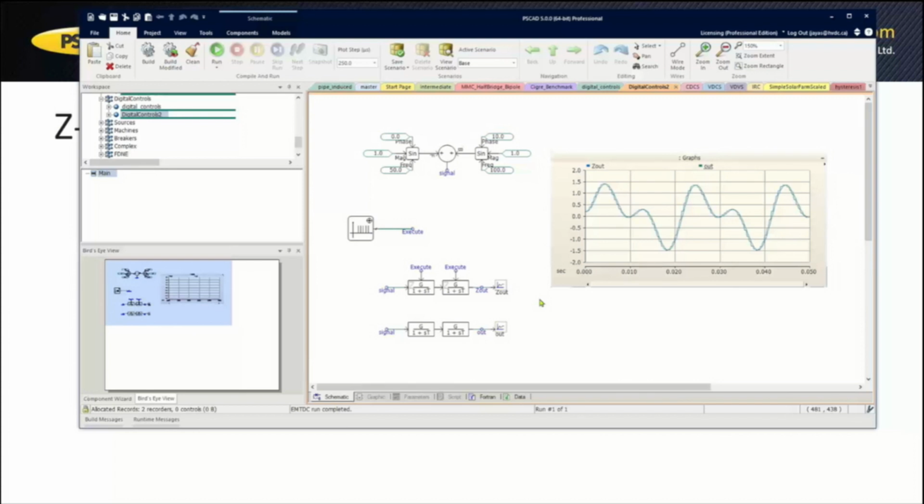So you have to compensate for that single time step delay in the feedback path when you're giving the clock signal. In this situation, the easiest would be to find the complete transfer function and use the nth order transfer function for the discrete controller.